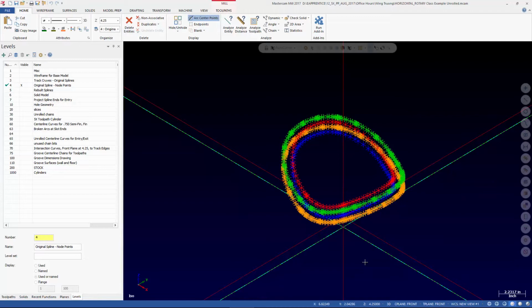What if we do this thing on a 5-axis machine? I mean, yeah, you could let it start at 90, but what if there's something hanging off on one side? What if you wanted to cut it where it only spans 60 degrees at a time? Do you know how to do that? By breaking up your geometry and operations and doing one at a time. Sometimes you have to make sacrifices for what you got, and I know you know about that.